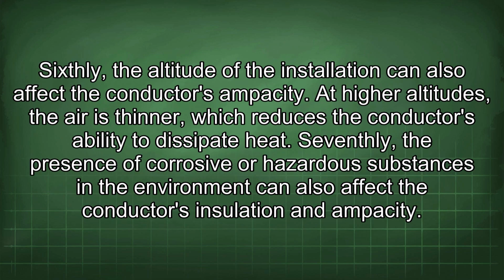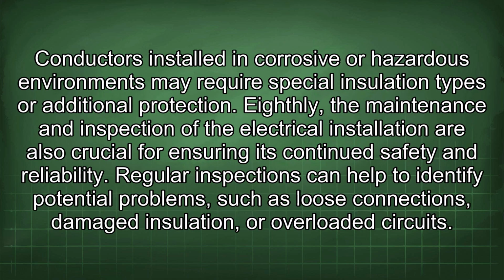Sixthly, the altitude of the installation can also affect the conductor's ampacity. At higher altitudes, the air is thinner, which reduces the conductor's ability to dissipate heat. Seventhly, the presence of corrosive or hazardous substances in the environment can also affect the conductor's insulation and ampacity. Conductors installed in corrosive or hazardous environments may require special insulation types or additional protection.